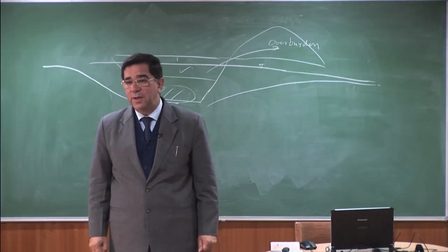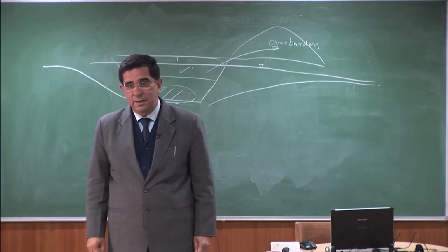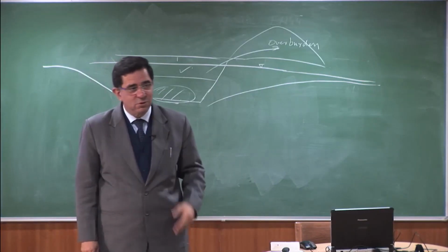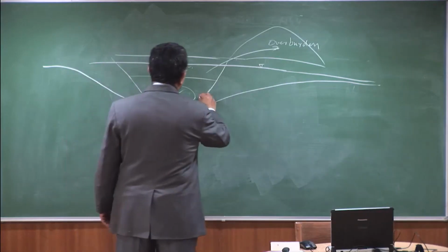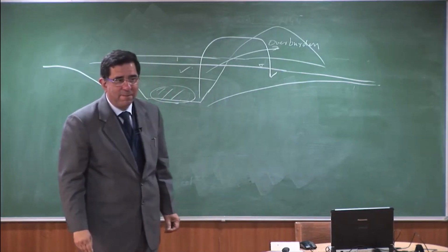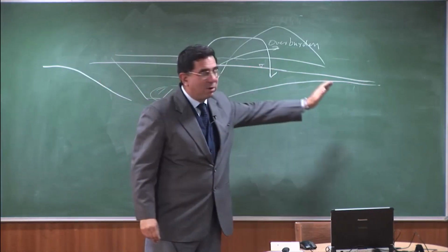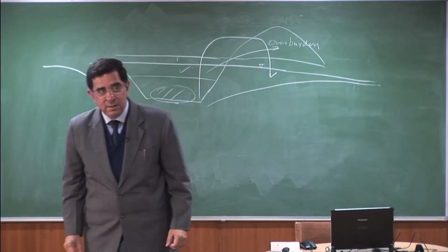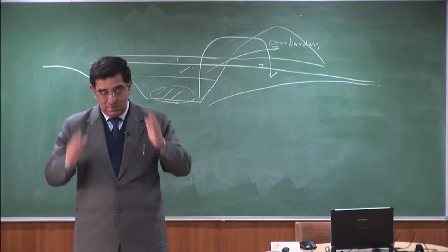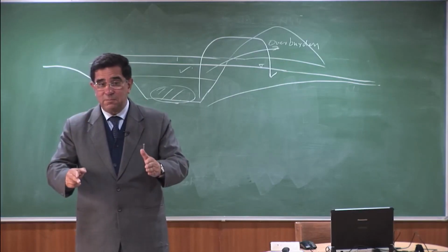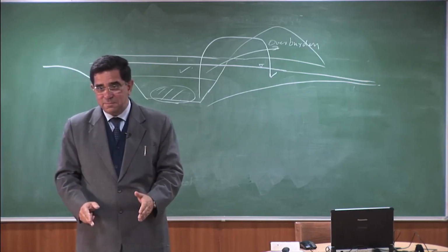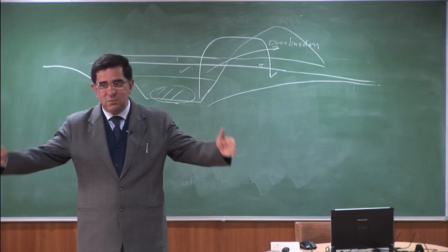So ideally, what should we be doing? Ideally, we should be maintaining the groundwater. And maybe we should, from an environmental perspective, remove the water and put back the water, so that this part of the water is not affected. That's what happens when the metro does excavation in Delhi. It removes the water from the excavated portion, but beyond 50 meters, it cannot deplete the groundwater. So there are extraction wells, and then there are injection wells at 50 meters.